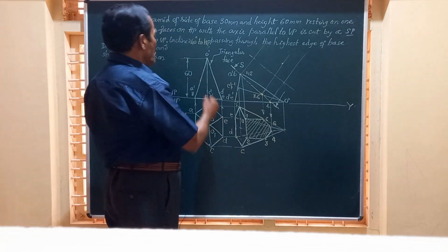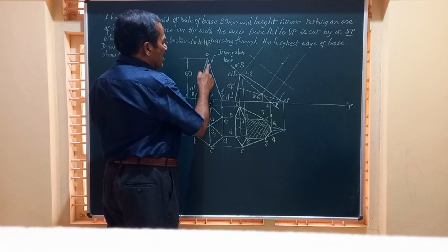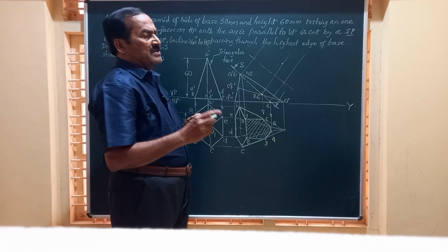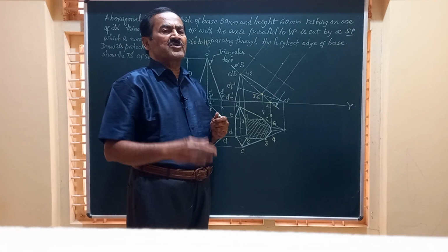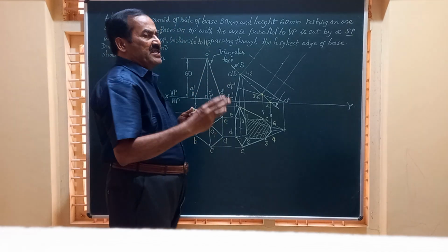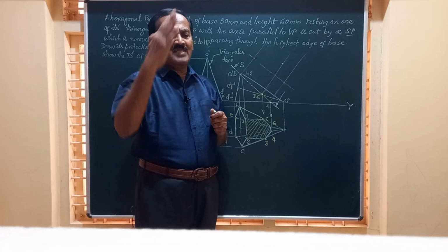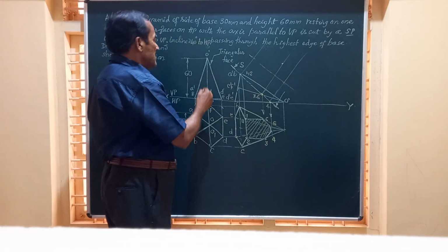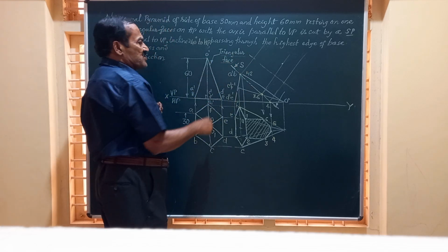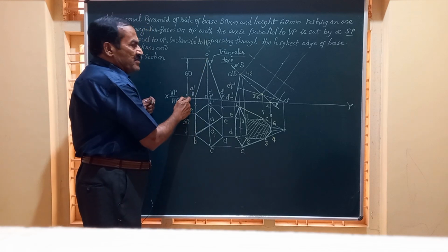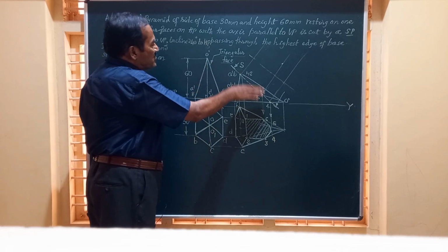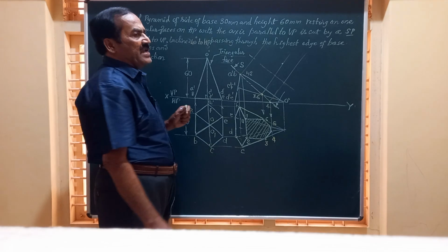Now friends, if you observe the front view, the last line, that is O dash D dash E dash, represents a triangular surface. And you can ask me how? Because there are 3 points, O dash, D dash and E dash. Whenever there are 3 points and above, that represents a surface. So here, this O dash D dash E dash represents a triangular surface of the solid. Even O dash A dash B dash also represents a triangular surface. Since we are going to tilt the object to the right, I am considering this O dash D dash E